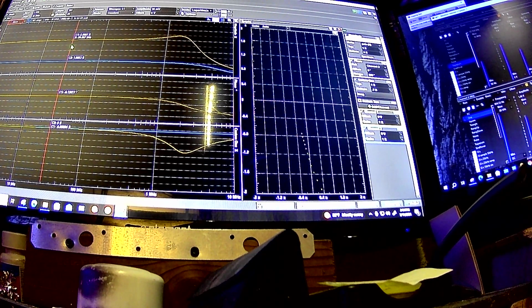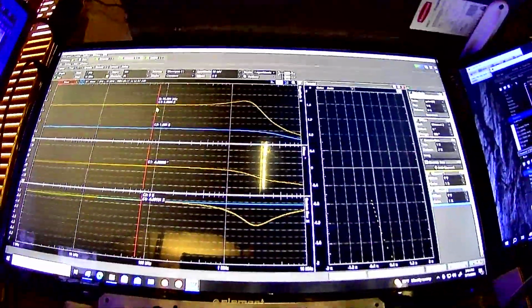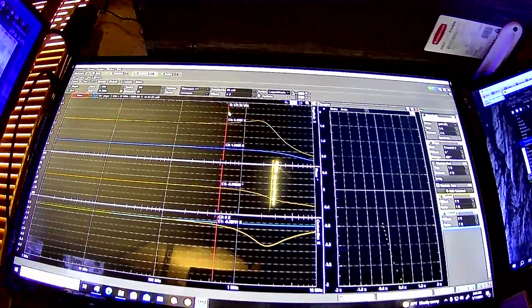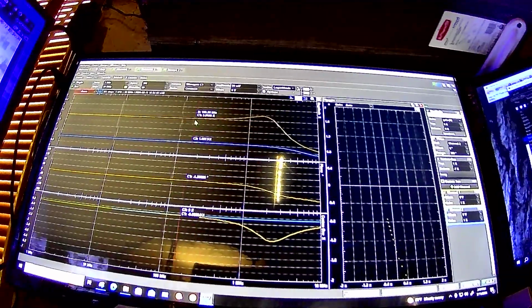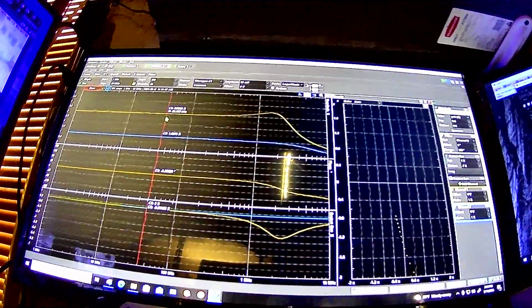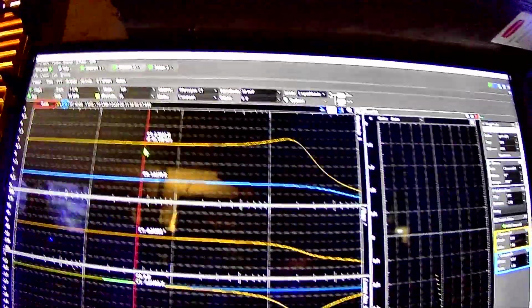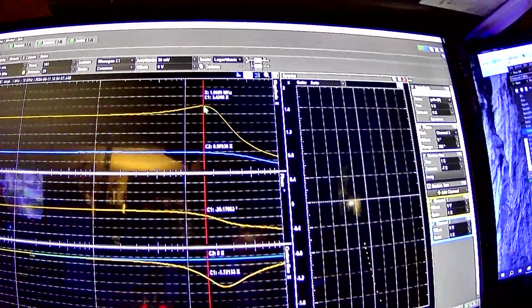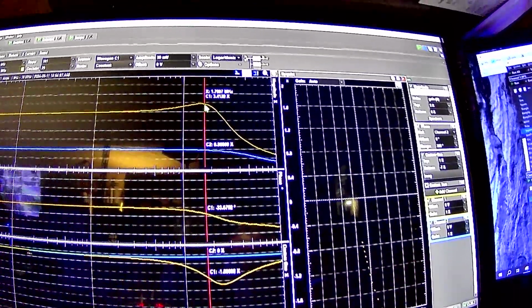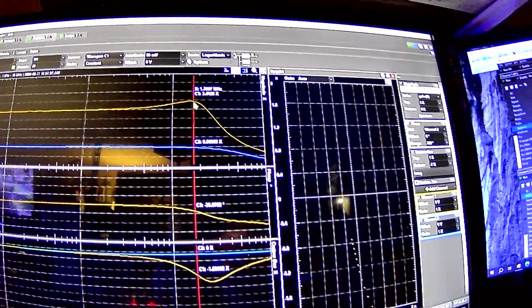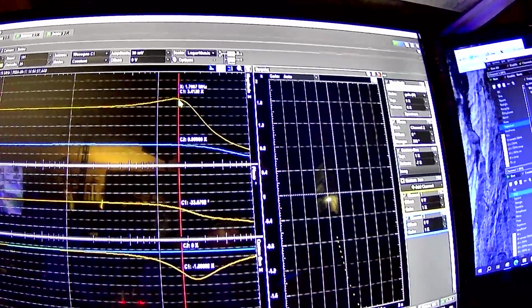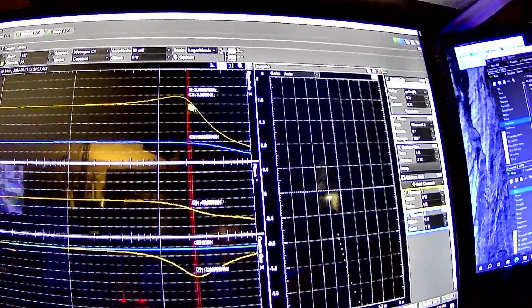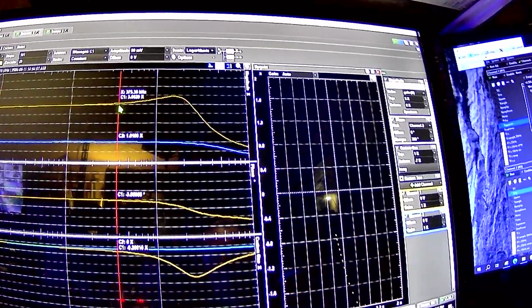Oh, additionally, on the 5532, I thought I'd run a spectral analysis on it here with the Analog Discovery. With a 50 millivolt input signal, you see our gain of three is pretty uniform across this, but then towards the end you get this peaking hump, and if you look closely at the op amp data sheets, all op amps basically do this.